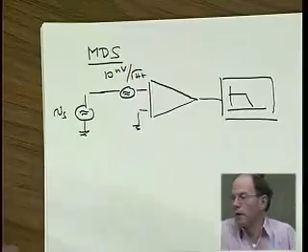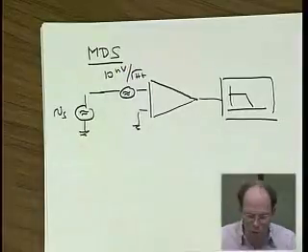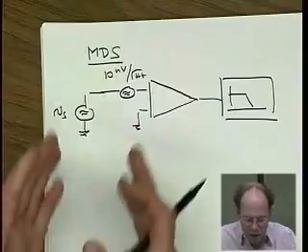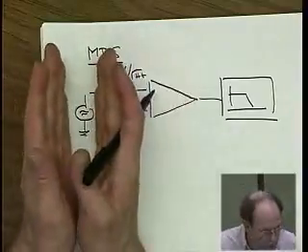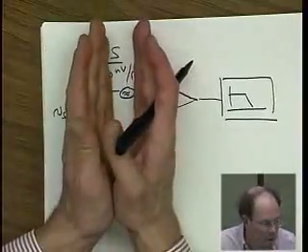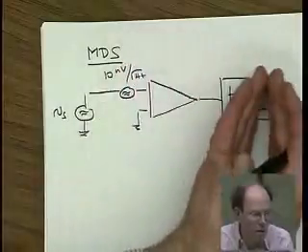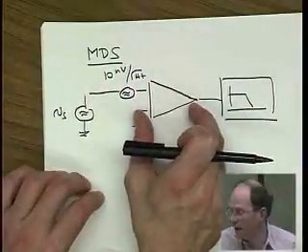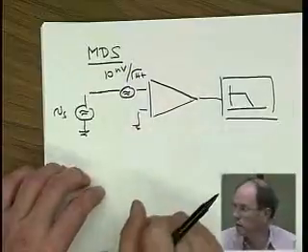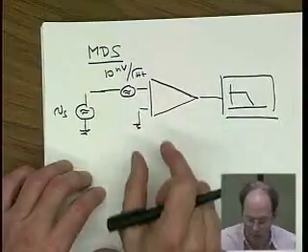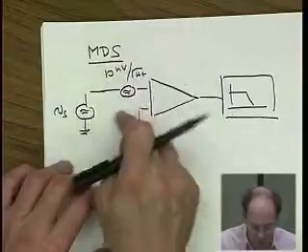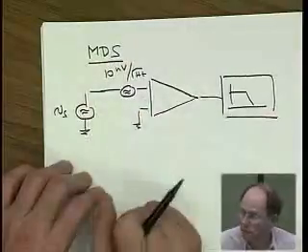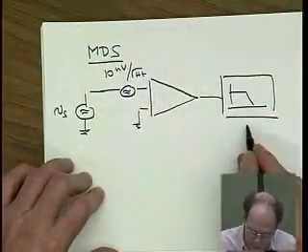In other cases, the bandwidth may be different, but you know what the bandwidth is. Then you know that the signal and the noise are going to travel through all this, and in the end, they're going to be amplified by the same factor because they go through the same amplifiers. In the end, you're going to be left with the portion of the noise and the portion of the signal that falls into that bandwidth. Let's call this bandwidth B.